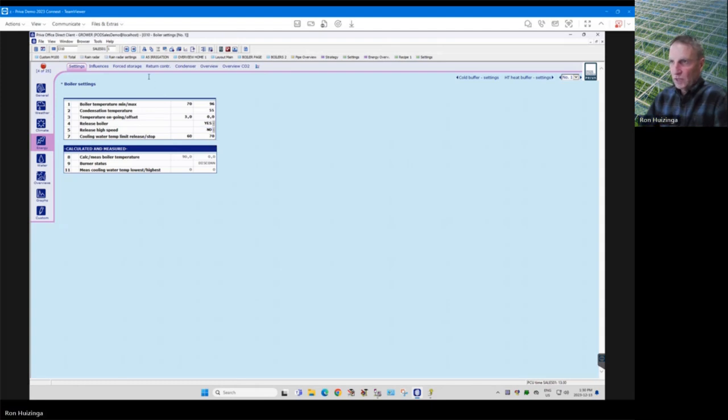Now, normally on the systems I work with, I get rid of that line because years ago, there were no variable speed drives. That's VFD, variable speed drive, that can speed up and slow down a pump. They were expensive years ago, so the boiler manufacturers would put a 2-speed fan on it, a high speed and a low speed fan. And that's where this line came in.